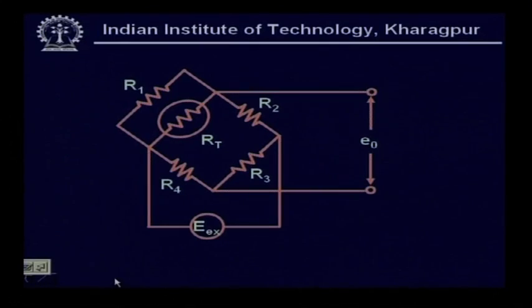These are other circuits of the thermistor which is used in a bridge circuit. You see here, there is a typical reason why we have connected a resistance in parallel with the thermistor. Now, as I told you, thermistors are nonlinear devices. So, linearity is a great problem with the thermistor. So, what they are doing, a common thumb rule, is that you use a resistance in parallel with the thermistor, right. So, what will happen, you see.